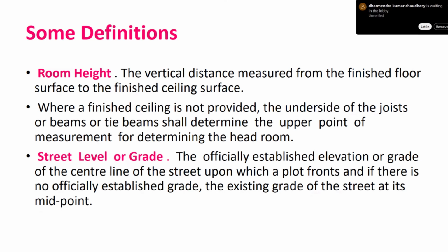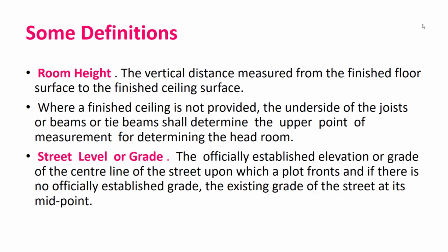Now there are certain things again, minimum depth. Now this was with respect to how many numbers you have to do. Now what should be the depth up to which I should go? Now, if you go by the definition, minimum depth to which the increase in stress level due to the foundation load is less than 10% of the in situ stress level. Now, this is, as you can say, a theoretical definition.